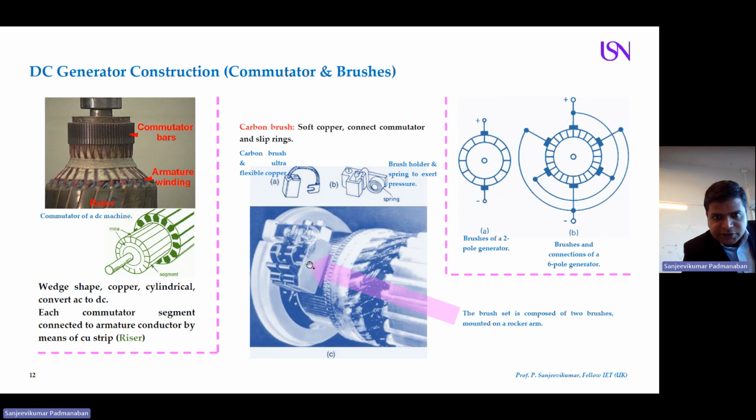As an example, you can see a large size machine. Now look at a large size machine, it is not exactly 90 degrees. Look here, they are slightly tilted. This is a small power machine, nothing will happen. Armature reaction is very less. It's a very small horsepower machine, very low power. That's why it is exactly 90 degrees. But it's a very high power machine, that's why it's tilted. You can see this is a complete set of your brush.